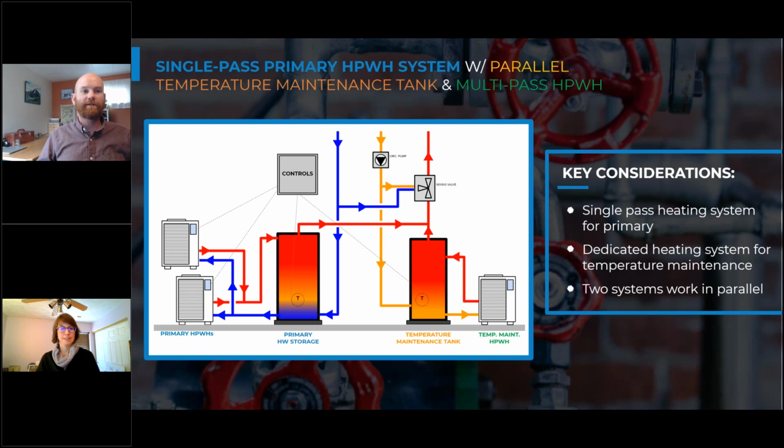It's also beneficial, at least from what I've seen, to use an electronic thermostatic mixing valve. So thermostatic is going to create a static temperature out. It's the goal. And electronic mixing valves are typically just faster to respond than paraffin wax or bellows or other more common historical mixing valves.